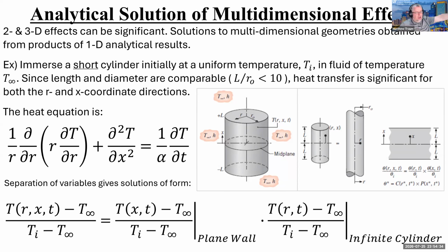Well, if you go all the way back to when the original equation was solved, remember it was solved by separation of variables. It's basically a differential equation, right? And you can add solutions to differential equations, right? And get the more complicated solutions, right? The homogeneous and non-homogeneous solutions. If you follow logically all the way through, all the math all the way through, this multiplying of temperature solutions, dimensionless temperature solutions, is like adding those differential equation solutions to each other, right? So it's mathematically identical. That's why this works.